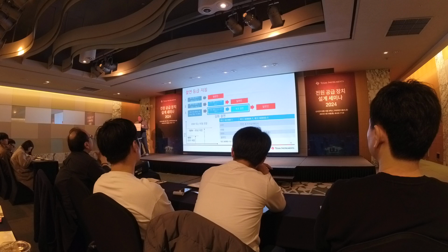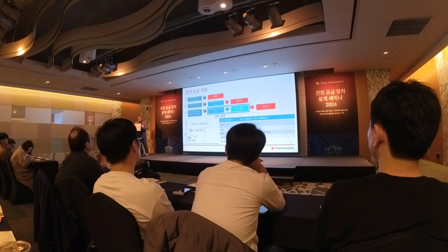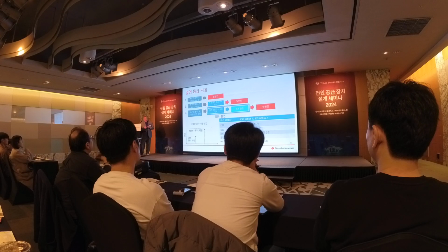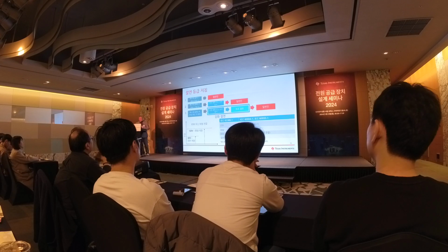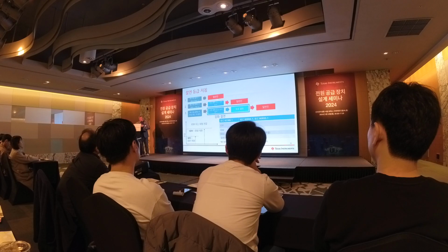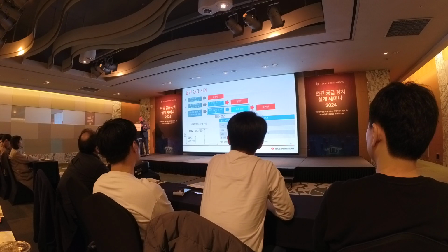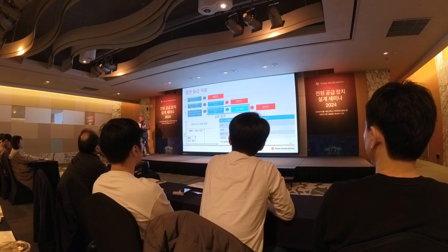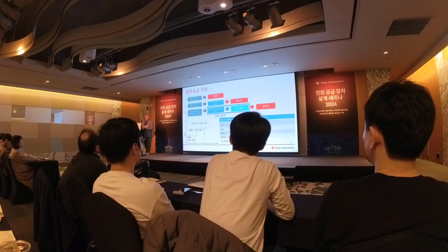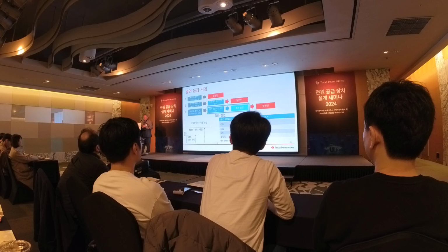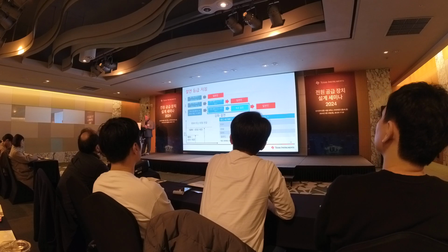This is related to telecom network voltage class 2 and telecom network voltage class 3 as well, over here for ES2. So for those, we need to have basic insulation between these voltages and the end user to protect them for safety purposes. And then we have ES3, which is considered hazardous voltage, above 120 volts. For those, we need to have supplementary insulation, which can be achieved by reinforced isolation.